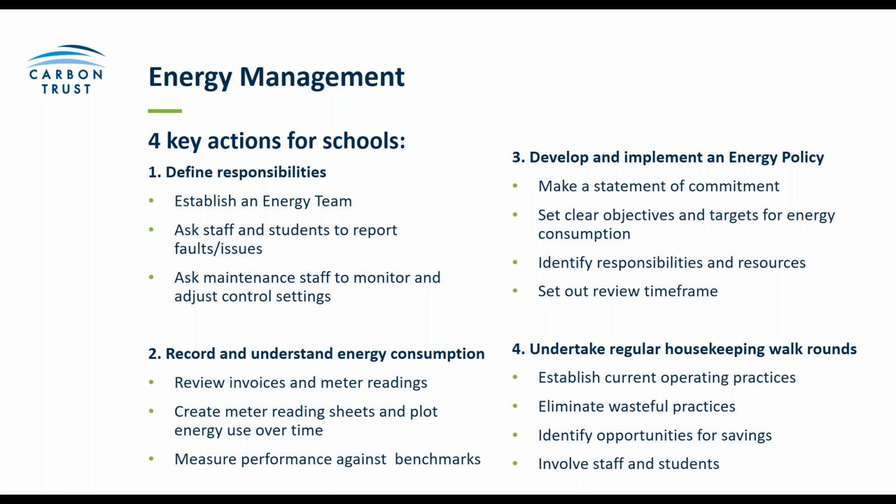It's also important to record and understand energy consumption, so making sure that meter readings are taken at least on a monthly basis, if not more regularly, depending on the size and complexity of the site. Also making sure that invoices that you receive from suppliers actually match the consumption that you are reading at site, identifying any issues there.